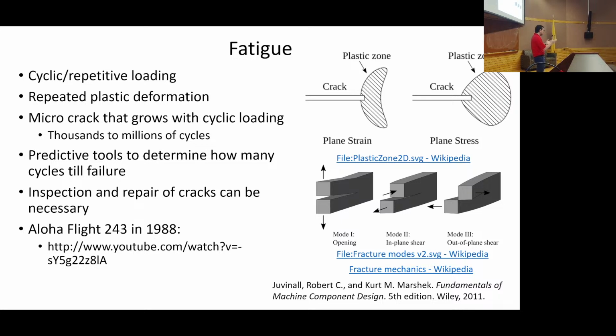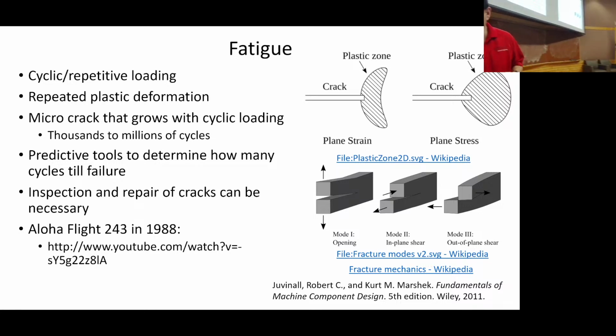If you have fatigue, the crack is opening and closing and it's propagating, and the effective cross-sectional area that has to carry all that load gets below essentially a static level of width or area that gets to a high level of stress, and then it will essentially statically fail. So there's this connection between micro cracks that can form and lead to failure.